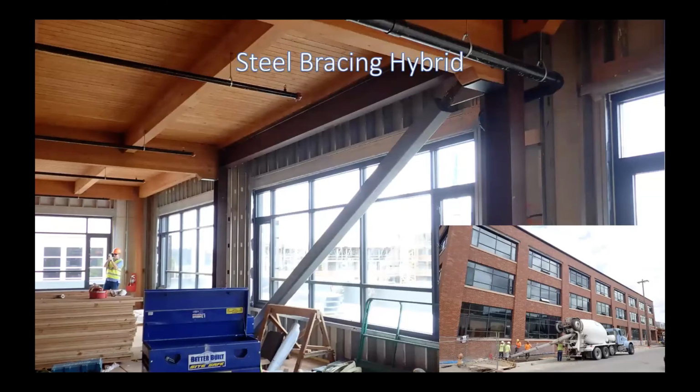In some cases, like in this building at the bottom right, you can see it's actually a brick building. They are not afraid of hybridizing with different materials like steel bracing if necessary, because you get the advantages of different materials. But they're not going to do a whole building in steel either, because there's so much advantage that timber can offer. And that's why they hybridize timber into this building that's braced in steel. So timber doesn't always have to act on its own. It can act with a concrete podium below in a hybrid form, or it can act with steel where it's appropriate. And I think we've got to be open-minded to use the best material for the best purpose wherever we can. So that's another bracing system.